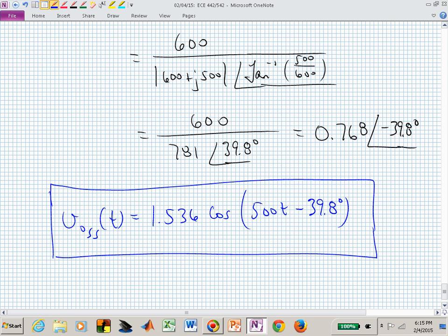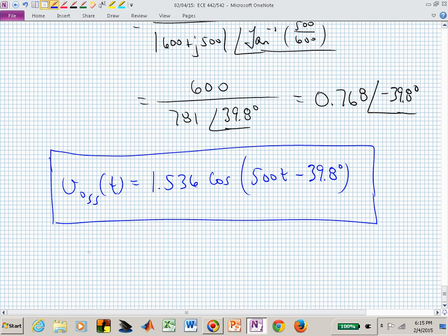We now want to find a linear difference equation so that you can now program that into your computer or microcontroller. You want to now build a low-pass filter in a computer, first order, with these same or similar properties.